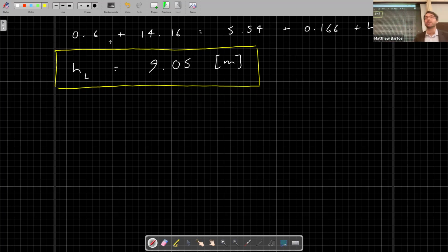Okay, but that's often a good thing. So like I mentioned, we're often interested in inducing a hydraulic jump because we want the flow to be less energetic, especially if we are discharging water into a natural channel. We want to reduce that kinetic energy as much as possible so that we can limit erosion.